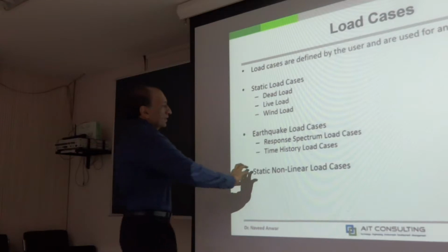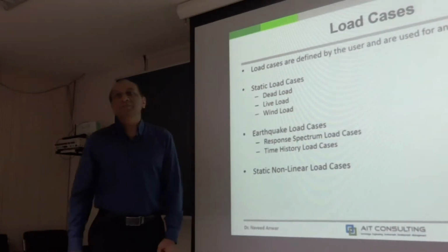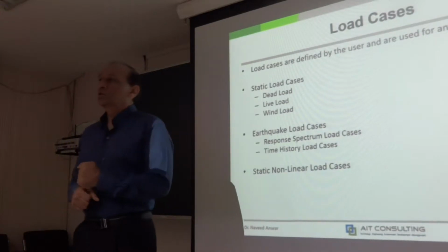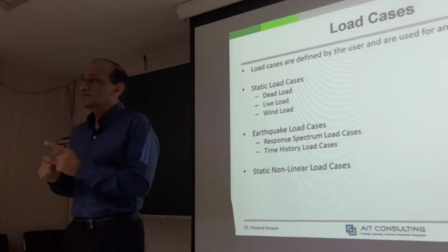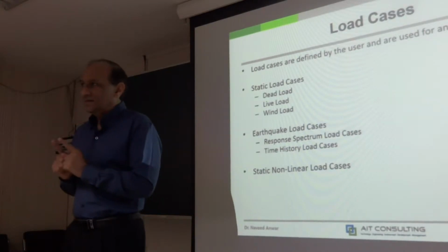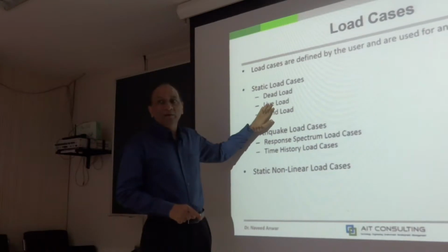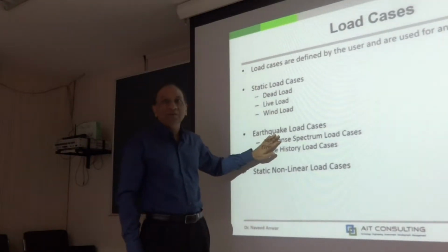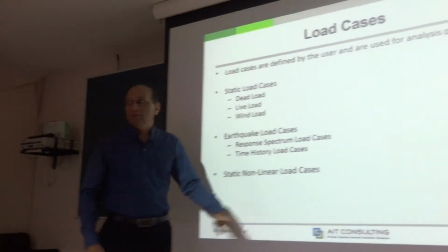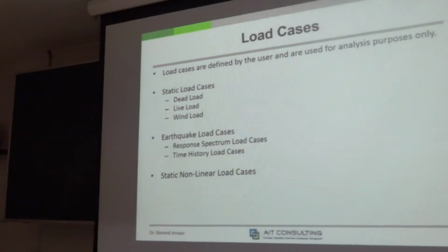So these cases and application gradually runs into hundreds of thousands in the end, right? And this is just each load case. Then we are going to combine dead load and live load and wind load. We are going to combine dead load and live load and earthquake load, which earthquake, and so on. So combinations will become even much more, far more than quake cases.